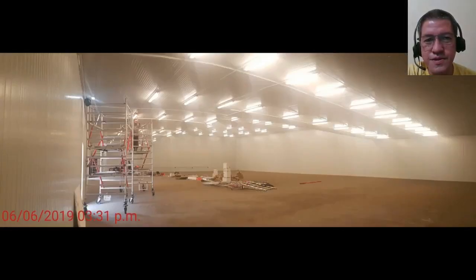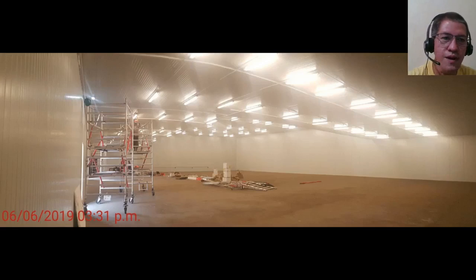And now this is the almost finished product, wherein most of the lamps were already installed, and we tested it by putting on the lamps, and we were able to acquire a lux of at least 300, which is the minimum for any warehouse of this type. How we were able to come up with the number of lamps installed on the ceiling is the objective of this presentation.